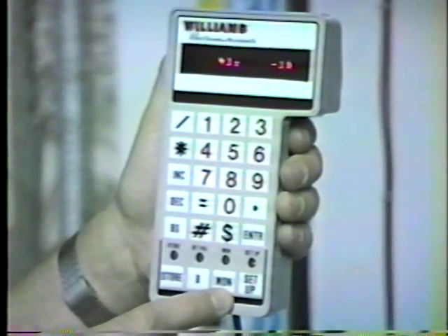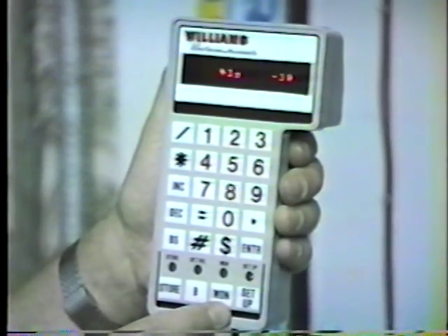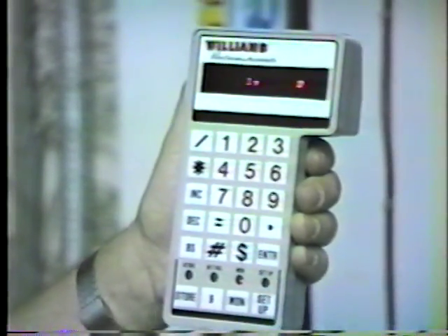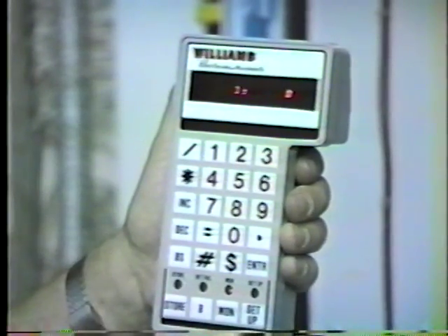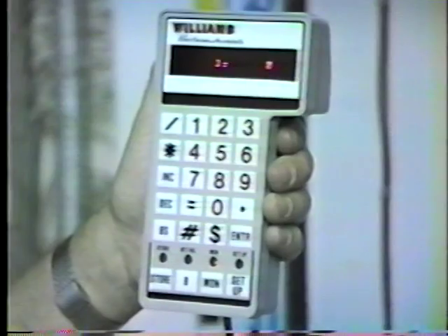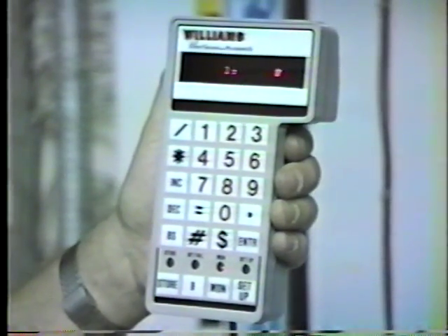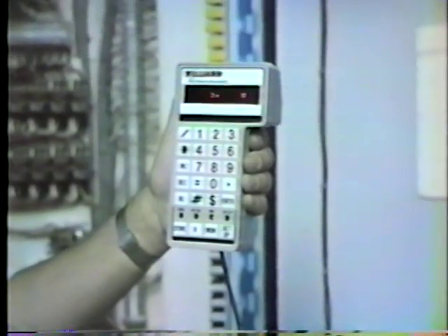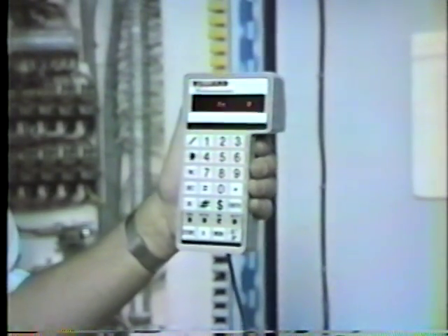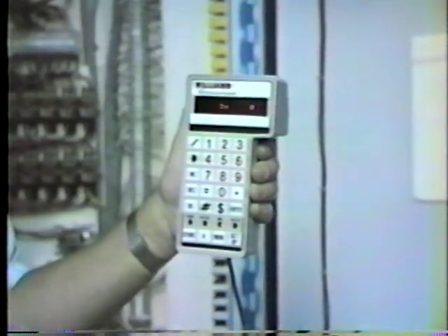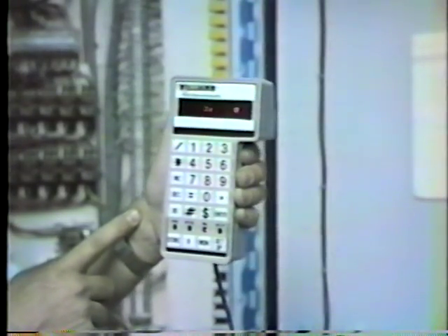Go ahead. The next mode is the monitor mode, and that aids us in checking out problems in the mill control. We push monitor, and similar to the setup mode, we get a channel number, which is an address in the random access memory of the computer. If the computer is operating, we can actually watch something change, for example the ideal delta pressure of the mill or the meter speed command. By holding down the monitor, each time through the computer's operating loop, which is about twice a second, it will update this display and we can watch parameters change. But that's strictly used in checking out internals of the computer capability.